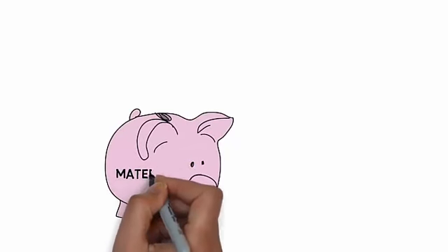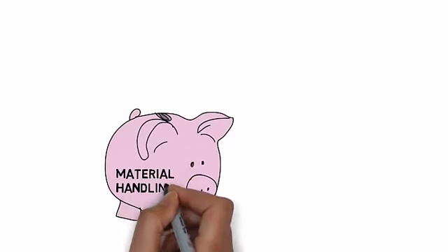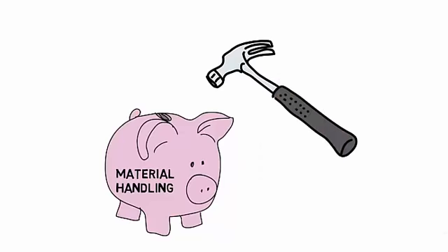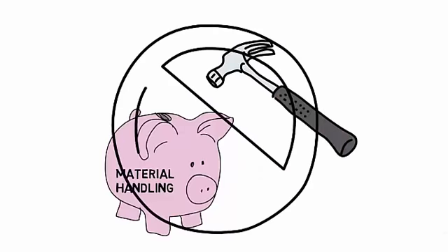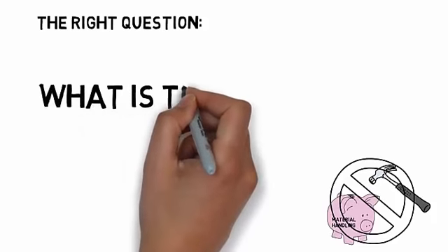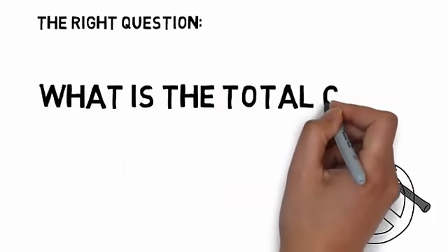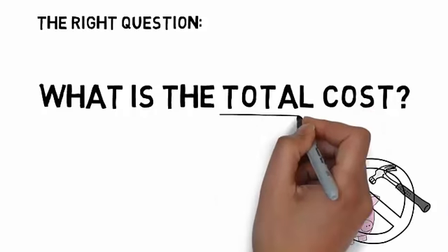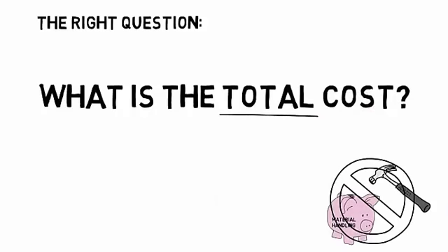Will a formal delivery route system increase your material handling costs? Well, that depends on what you're doing today. But it's also the wrong question. The concern from a company perspective should be on the total cost, including operator efficiency, quality, and space utilization. The total cost to the company should go down. So let's get into designing a delivery route step by step.